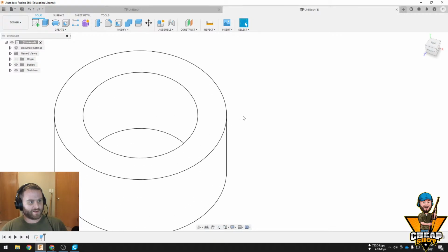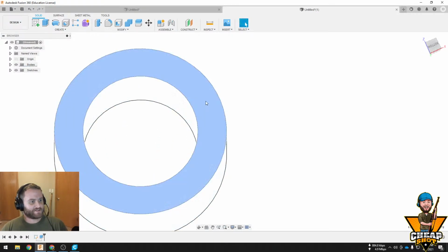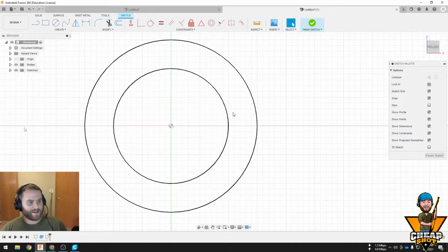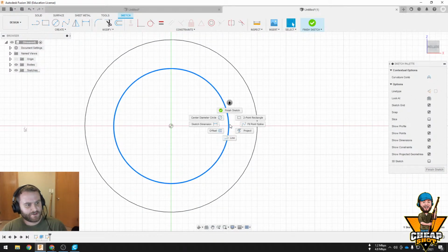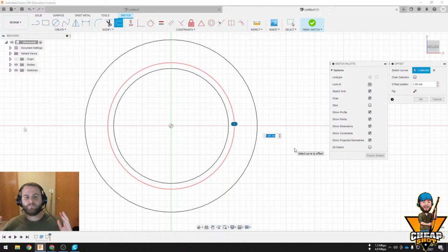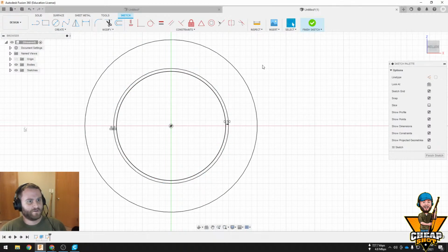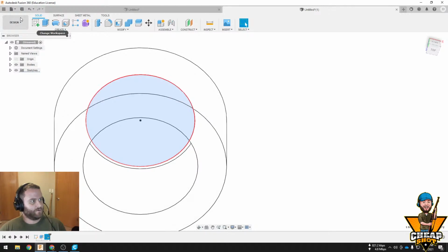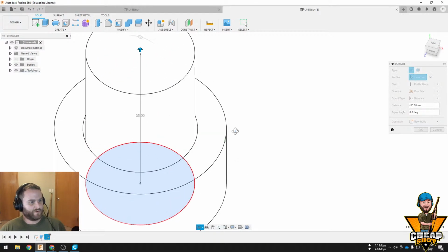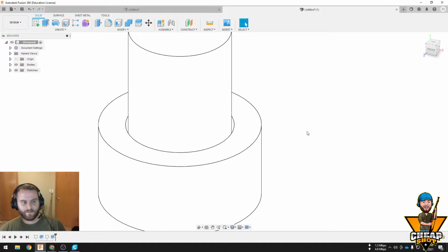Another thing, Travis, is when you're doing a fit, let's say I wanted to find a fit for something that goes around on the inside. I can sketch on this plane, right click this down to sketch, and offset it. This is perfect for making wall lines. If I want 4 wall lines at 0.8 thick, you can do this to make it 0.8 thick or 0.16, so you have 8 wall lines, 4 on the inside, 4 on the outside, and I can make this negative 0.5,